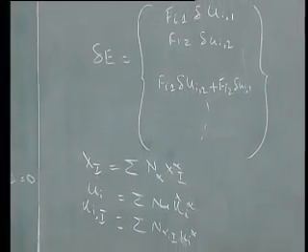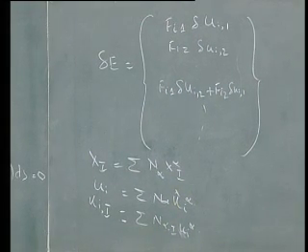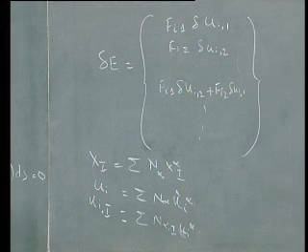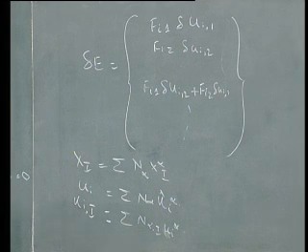Okay. Now what we do is substitute this into this expression in order to get a B matrix. Actually let us just do that and see what we get. Is there any question so far? Now let us write down for each of the nodes. Let us take a 3-dimensional problem, because this is a 3-dimensional element that we are looking at, because delta E we have written as a column vector with 6 entries.